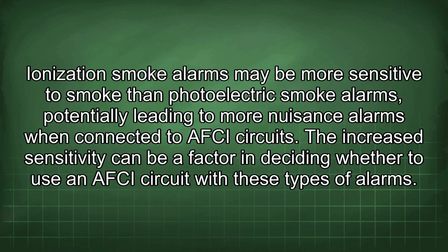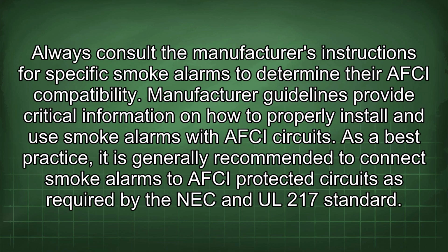Ionization smoke alarms may be more sensitive to smoke than photoelectric smoke alarms, potentially leading to more nuisance alarms when connected to AFCI circuits. The increased sensitivity can be a factor in deciding whether to use an AFCI circuit with these types of alarms. Always consult the manufacturer's instructions for specific smoke alarms to determine their AFCI compatibility. Manufacturer guidelines provide critical information on how to properly install and use smoke alarms with AFCI circuits.